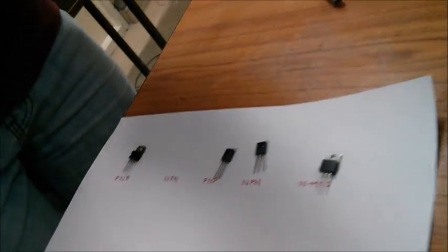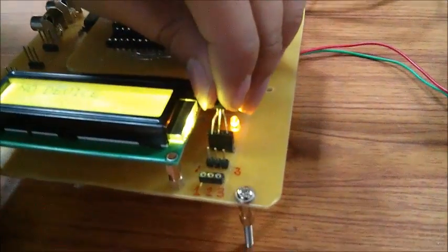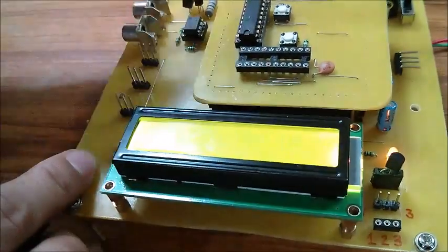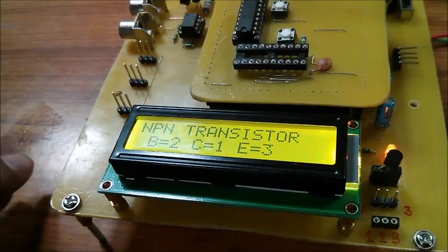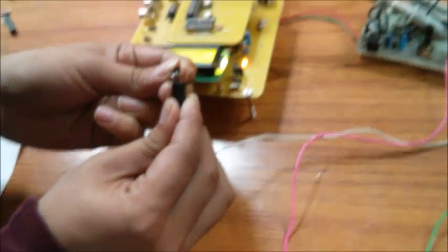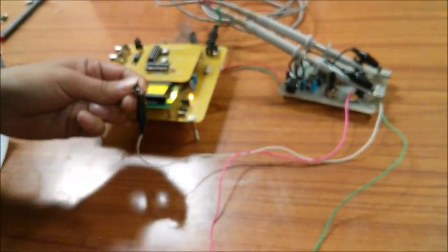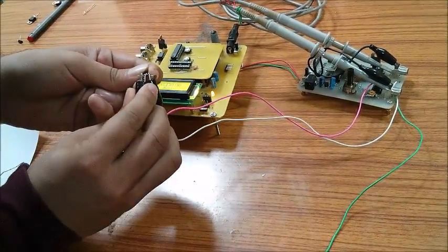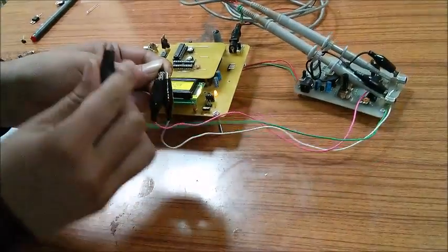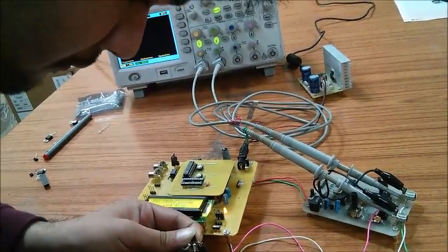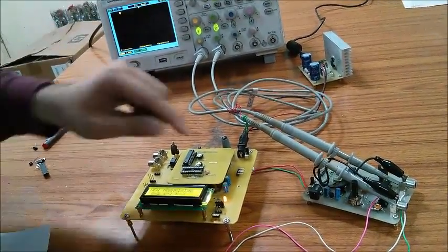Now we are going to demonstrate the tracer part of our project. For this, we need an oscilloscope operating in XY mode. We have taken an NPN transistor and firstly we test it for its legs using the tester circuit. The oscilloscope probes of channel X and Y have been connected appropriately to the tracer circuit outputs. Particular leads of the tracer are connected to the corresponding leads of the DUT. Switch on the circuit and observe the output on the oscilloscope. The oscilloscope is adjusted till a proper curve is seen on it.